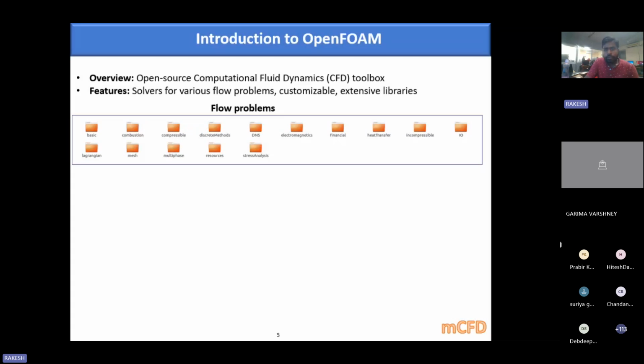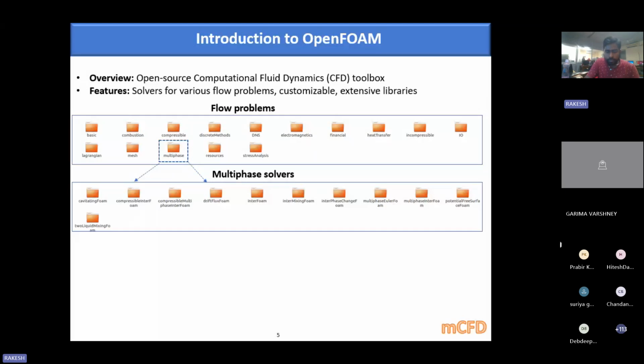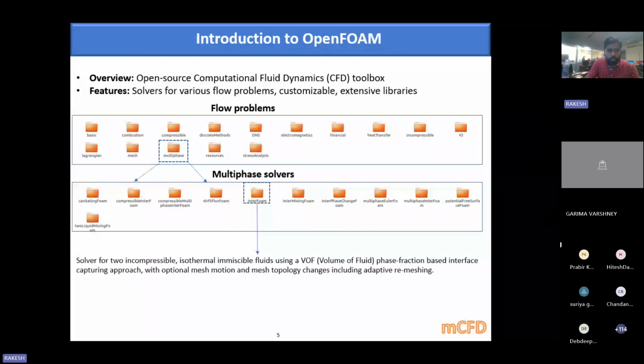We can see there are different categories of solvers in OpenFOAM. Among these, we are getting into the multi-phase solvers, which come with different criteria. Among these, we are getting into interFOAM, which is used for two incompressible, isothermal fluids and uses the VOF method for phase interface capturing.